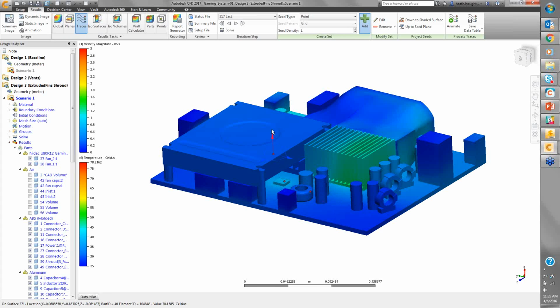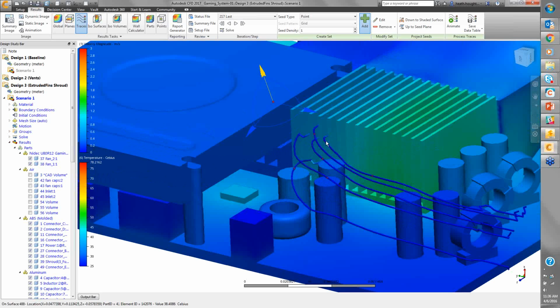And actually, what's even cooler, even while I'm adding them, I can start manipulating where they're located, and we'll see dynamic updates of those traces as we do it. So it's much easier to see where the flow is coming and going. This triad's manipulatable, and I can pan, zoom and rotate that triad. So that was just a little demonstration on point. As a matter of fact, I'm not done adding. I could continue to add more points and manipulate that data set as I see fit. Just a really simple, easy way to manipulate the trace seeding for one aspect of it.